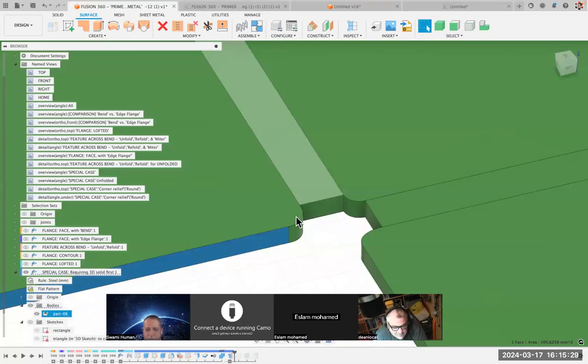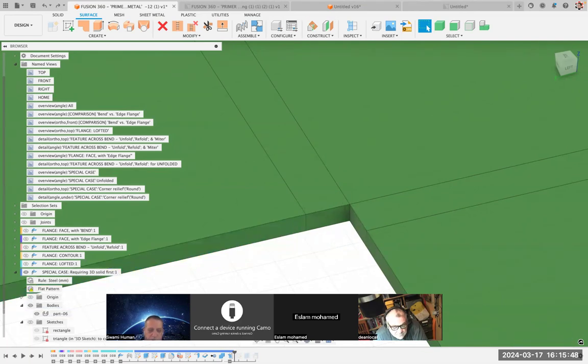And this is where you're doing your bend relief. So when you're doing the bend and you're deforming the material, it's going to stretch and compress in certain ways. And if you don't make a certain geometry in here, it won't do it well. Won't do it the way you want it to do. And so if we go back and undo to where we were, we can make what's called a round.